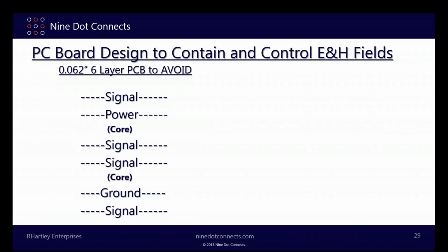There's this huge dielectric space, even bigger than in a conventional 4-layer board. It has high inductance and low capacitance. It has very high impedance, because it's such a wide space. The energy for power delivery comes from that large dielectric space. Well, what else is occupying that large dielectric space? All the signals on 3 and 4. Their fields are also in that same dielectric space.